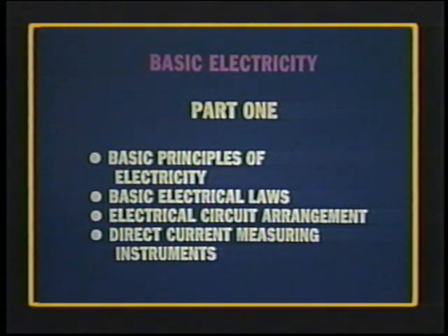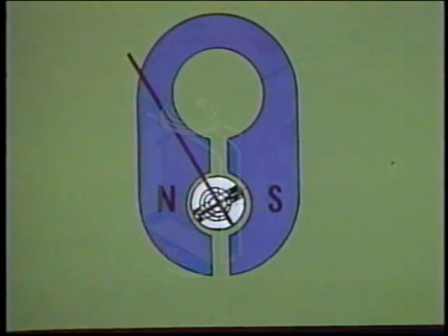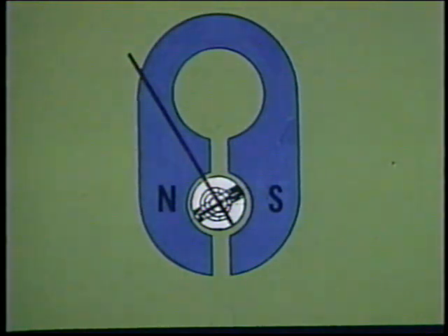In order to work with an electrical circuit, we need tools, specifically voltmeters, ammeters, and ohm meters. Most indicator-type measuring instruments use a D'Arsonval or Weston movement, in which the current to be measured flows through tiny hairsprings into a coil, which is suspended in jeweled bearings and is free to rotate. The electromagnetic field produced by this coil reacts with a strong permanent magnet field and produces pointer rotation proportional to the amount of current.